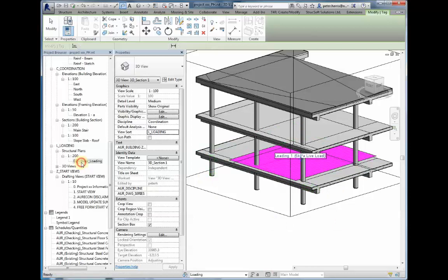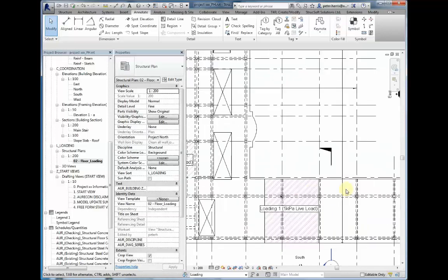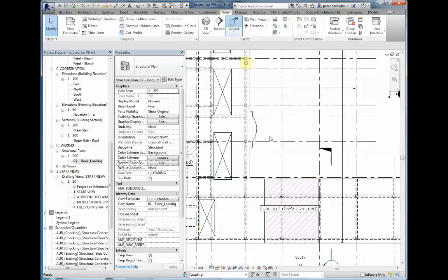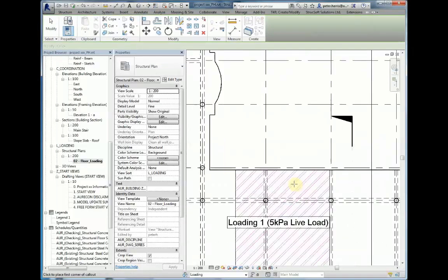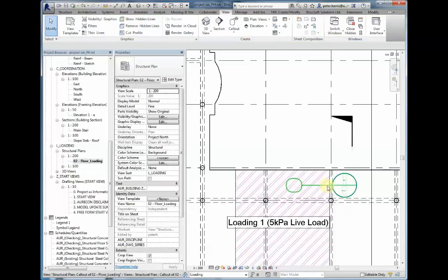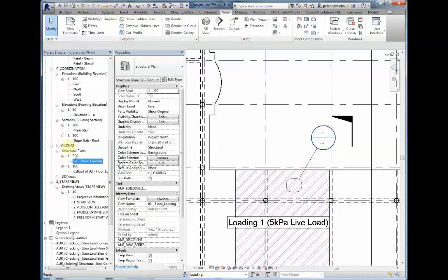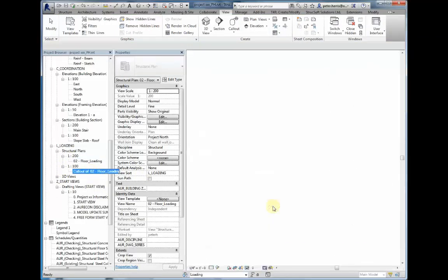So to do this, because it's a live active component, we need to, off our plan view, create a call out. Under the view tab, doing ourselves a call out. Certain size. Okay, this call out, just ensuring it's all sitting in the loading area, which it is. Going to now this call out.